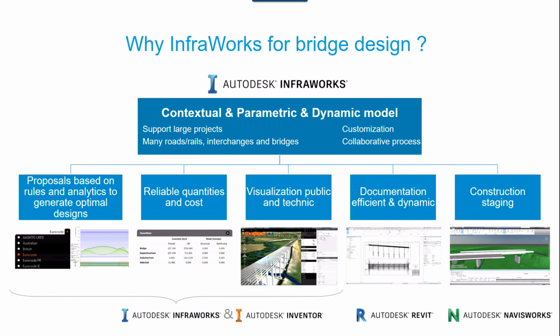The visualization, of course, is by default in InfraWorks. You don't have to do anything more to be able to share and to communicate on your technical proposition. For the documentation, we will use the link between InfraWorks and Revit to use all the advanced functionality of Revit to create the technical documentation. And for the construction staging, for the planification, we will use Navisworks, and we will import the model in Navisworks to use the timeliner in Navisworks to propose the planification.